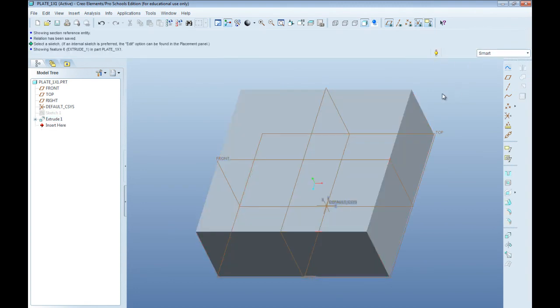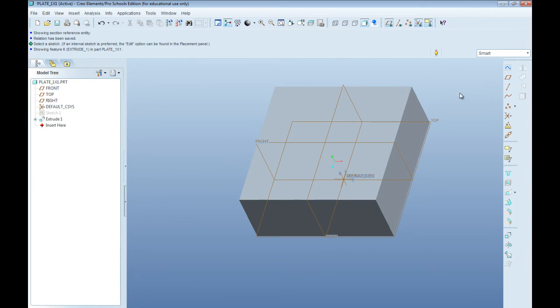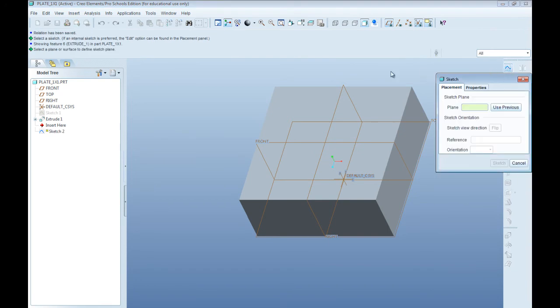So we have our brick now. The next thing we'll do is create another sketch to create the stud on top of the brick, which, of course, allows the Legos to interlock and mesh so that they don't fall apart. Click sketch again. From our original 3 datum planes in our sketch, we've created extra datum planes that can also be used to draw features or sketches on.